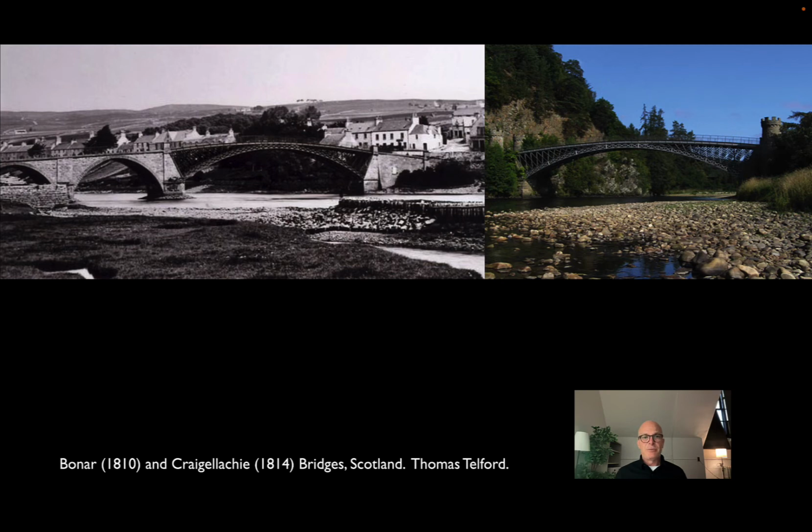And you can see that particularly in the Bonar Bridge on the left, where the approach arches are built of masonry and obviously are incredibly heavy, requiring huge foundations to support the dead weight of those approaches on the river soil below. Whereas the iron bridge, the part that Telford is doing in the middle, is incredibly lightweight and incredibly porous, so that floodwaters can flow right through the truss or the web between the arch and the deck.